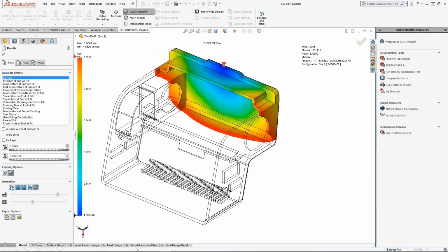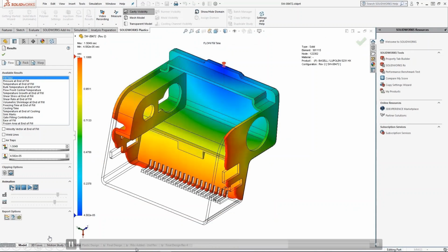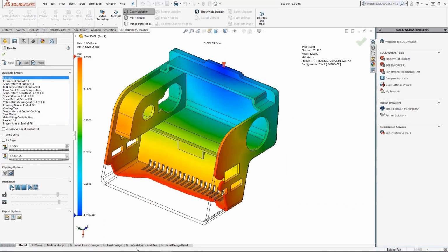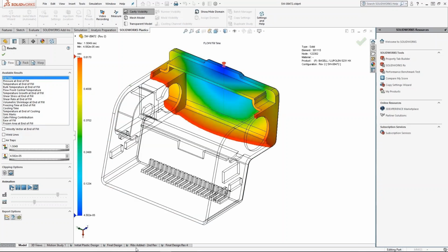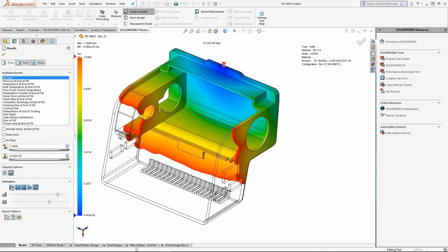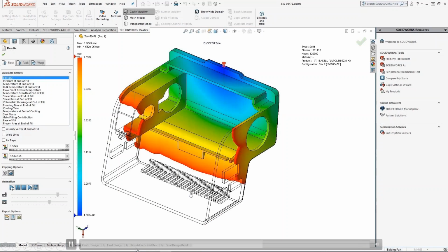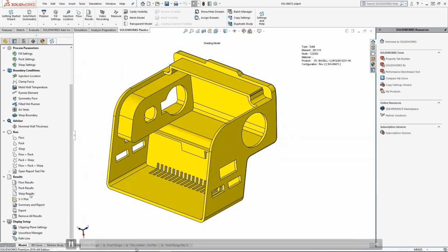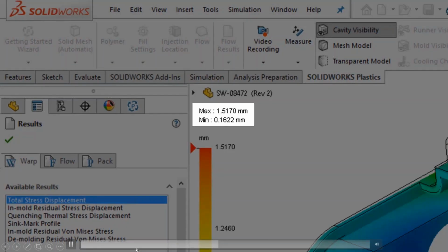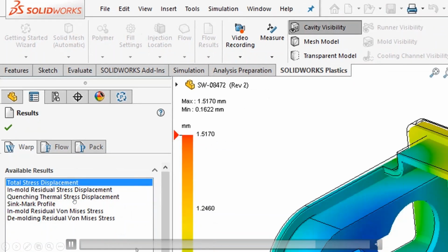So let's start with plastics. This is SOLIDWORKS Plastics, and it's very simple to see the filling. In this case, we can just leverage the 3D model to see if it's injectable, and of course the timing, and whether we can have some problems, so we can make a decision to have a better design. Also, with Plastics Premium, they had the displacement results, the warpage results.